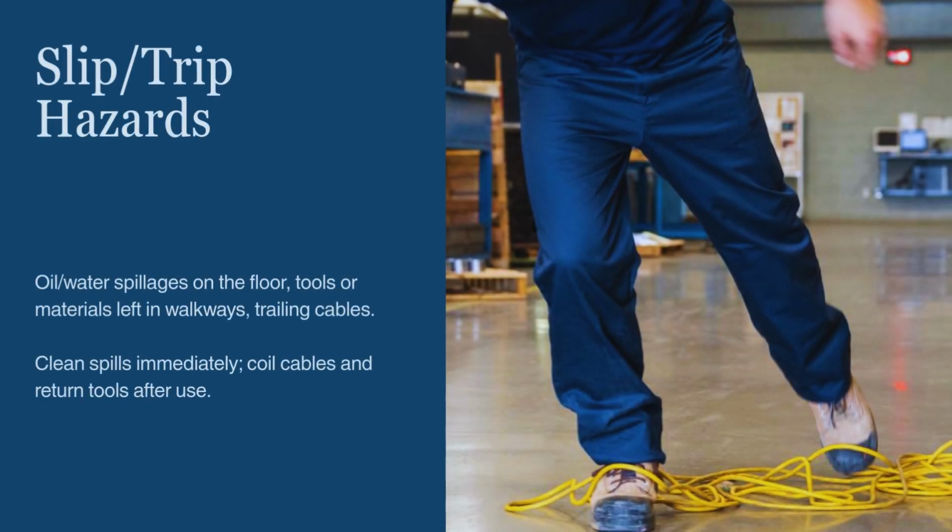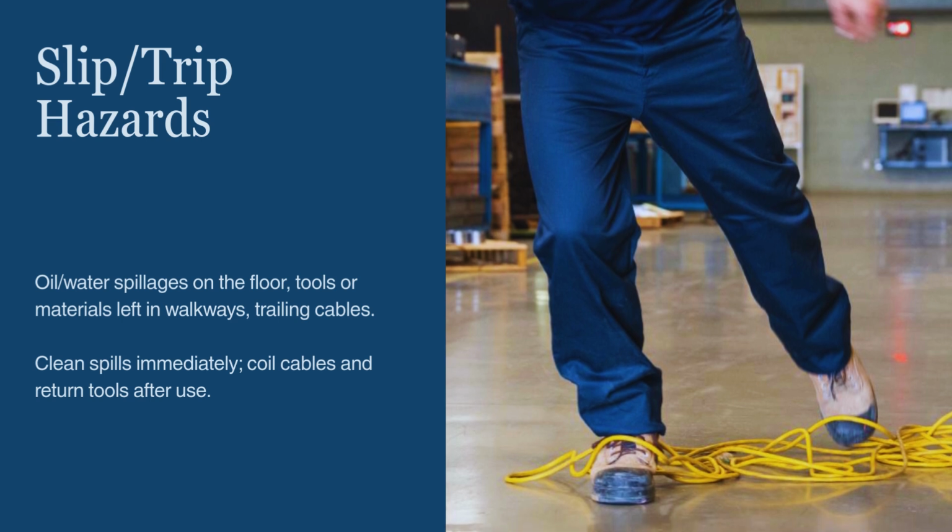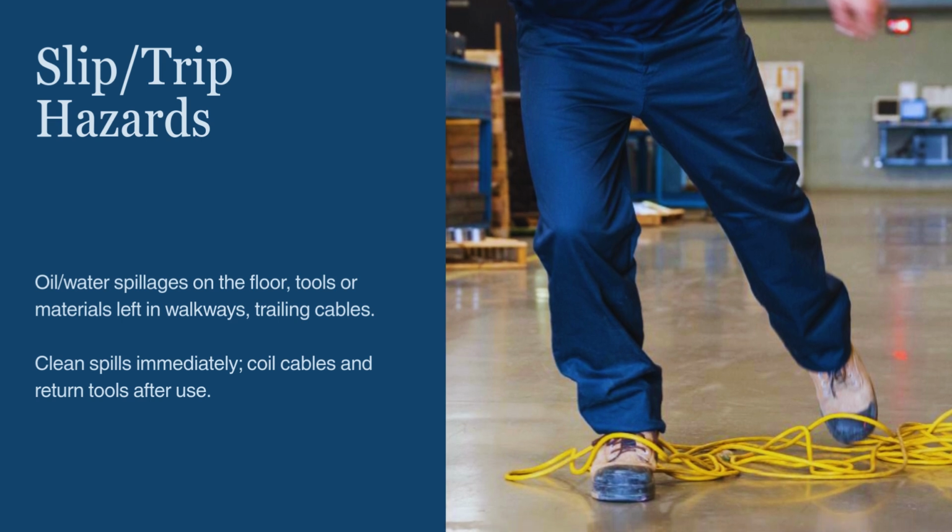Finally, we have slip and trip hazards. These hazards are usually caused by poor housekeeping. Examples include tools left on the floor, oil or water spills, metal offcuts, and trailing electrical cables across walkways. Slip and trip hazards can lead to falls, fractures, and serious injuries. Keep floors clean and dry, store tools properly after use, and ensure all walkways remain clear. Remember, recognizing hazards and taking action to control them helps create a safe, organized, and professional workshop environment.